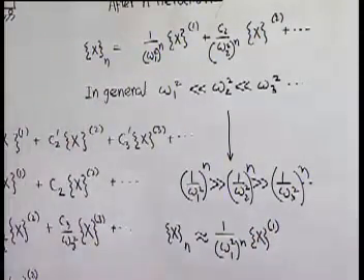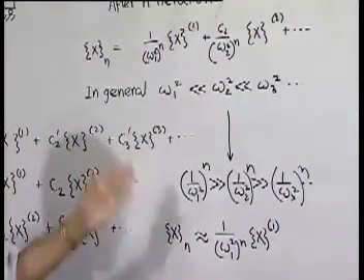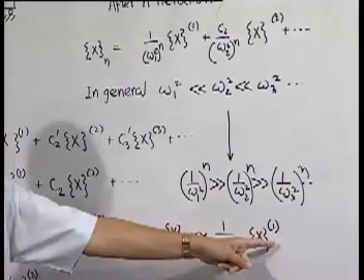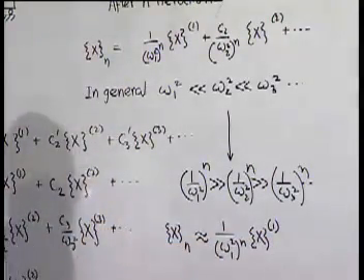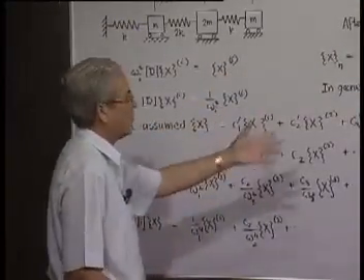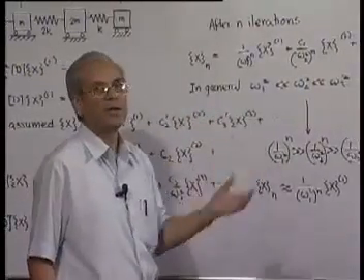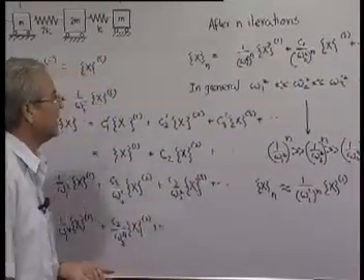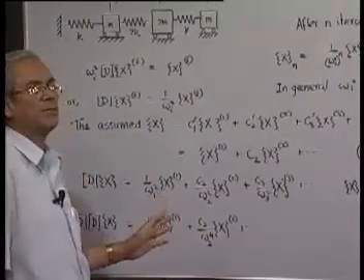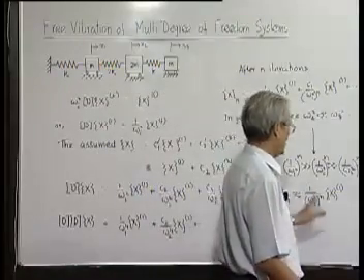What does it mean? Forget about this. As far as the mode is concerned, because of the ratios of the various terms, it really approaches the first mode, and the corresponding frequency becomes the first natural frequency. That is why, whatever may be the initial value, if it is closer to the first mode, then the number of iterations will be less. If it is very different from the actual first mode, it will take a longer time to converge, but it will converge to the first mode.